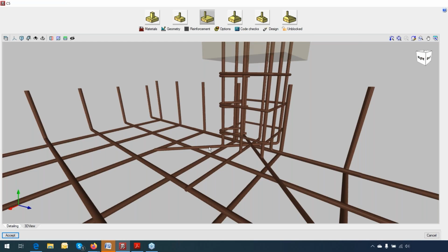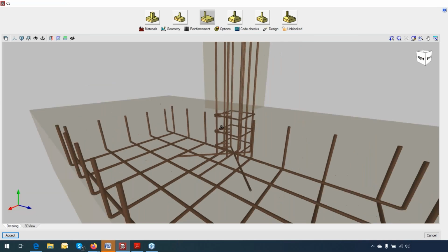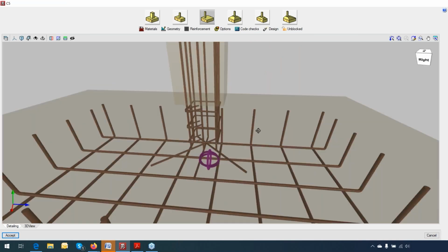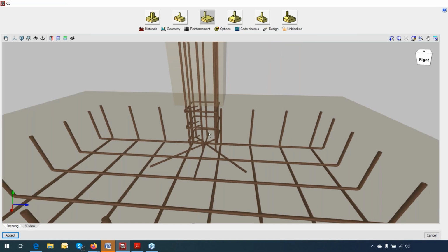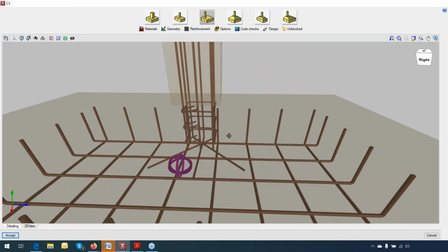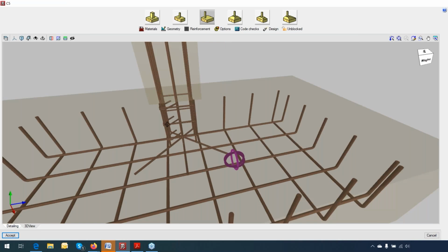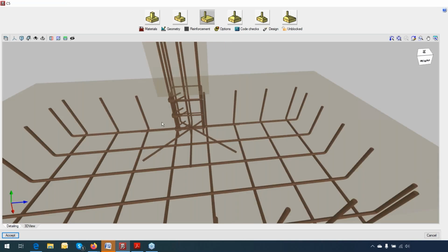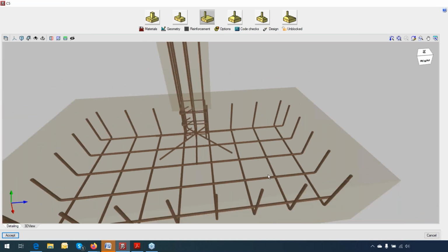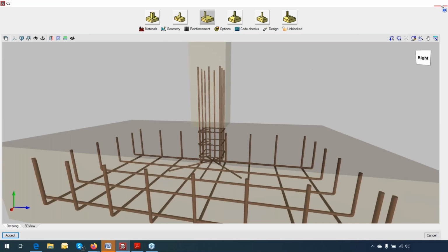In the design process, we must select this section, and it goes by the bar. So for the vertical bars, the only way to change it is going into the column designs. In the column designs, you can modify the bar because it gives you the best bar. For example, you go for one inch diameter, and over there you can change it for something with a lower diameter, and in that case, you can get a better geometry result. This is one of the solutions.